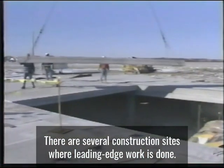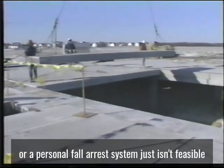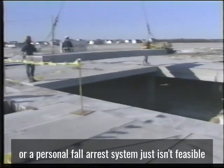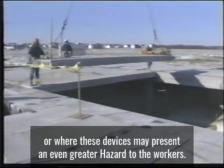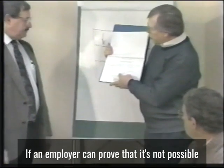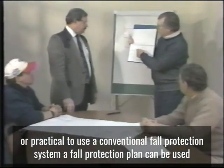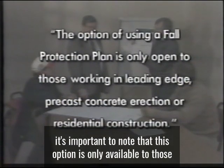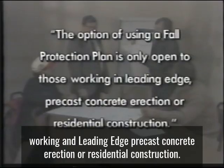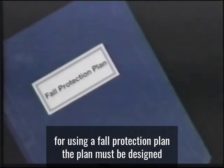There are several construction sites where leading-edge work is done, for example, when the use of guardrails, safety nets, or a personal fall arrest system just isn't feasible, or where these devices may present an even greater hazard to the workers. If an employer can prove that it's not possible or practical to use a conventional fall protection system, a fall protection plan can be used. It's important to note that this option is only available to those working in leading-edge, precast concrete erection, or residential construction. Here are the requirements for using a fall protection plan.